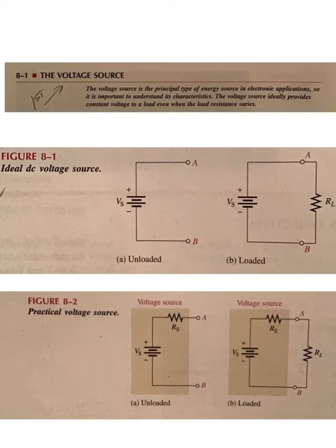The thing that's sitting on your bench in the class has a series resistance tied to it called RS, and to be useful as a voltage source, its value is small, 5 ohms, 10 ohms, something small. If it starts getting into the kilo ohms range, it starts affecting the performance of the circuit it hooks up to. In other words, this internal resistance steals voltage from the source.